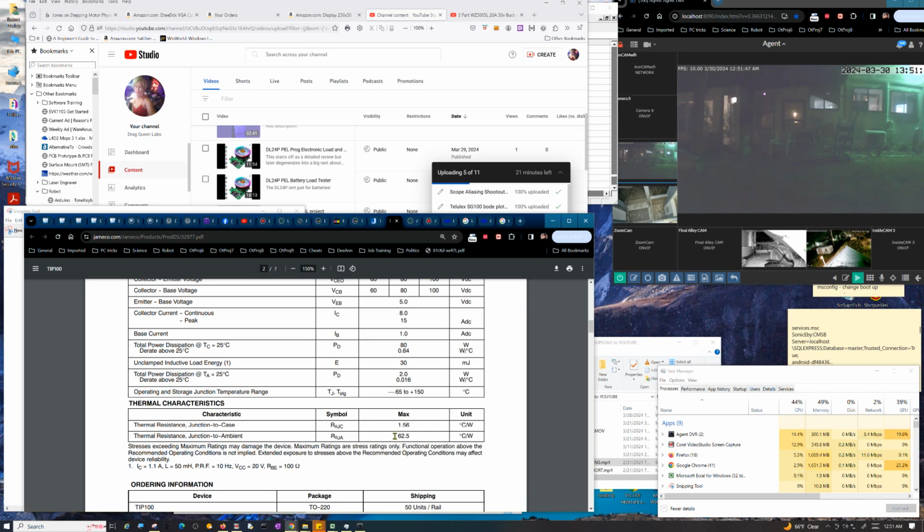So let's say we had this transistor mounted on a horizontal circuit board with a bunch of other components, and maybe other components on the side. You still want to take the temperature near the base of the component, because that's your cooling air. But probably a little above the circuit board. My recommendation would be a quarter of an inch, maybe half an inch above the circuit board, but also a quarter of an inch to half an inch away from the transistor itself.